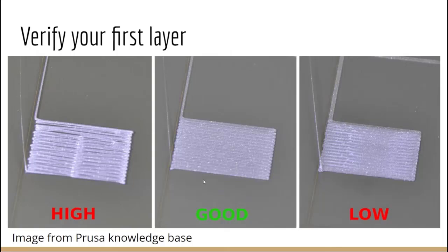Especially nowadays, it's more common for printers to have a bed leveling sensor, but you most likely still need to do an offset to get the layer perfect. Now, if you look at these three photos, you can see stringing, where the strands of plastic are individual. The sides of each strand haven't overlapped enough to stick together, so they're all separate and stringy. But if you look in the middle, they've compressed the perfect amount. The little white lines in between are where there's a bond between layers sideways. And if your print head is too low, you see these little flares of plastic. It's squishing too much. Like if you took a piece of Play-Doh or putty and pushed down in the center, it's going to curve up and around. That's the same thing your plastic's doing here.